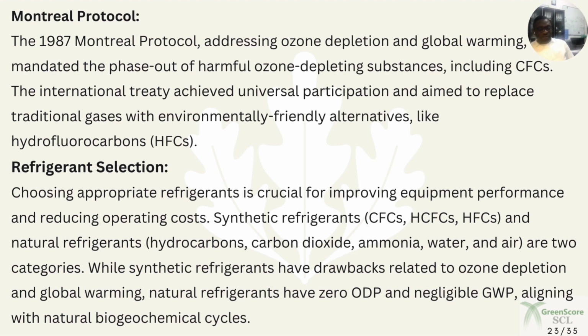The first group have their drawbacks because of their ODP and the global warming potential. Whereas natural refrigerants have zero ODP and global warming potential that is negligible and is in alignment with natural biogeochemical cycles.